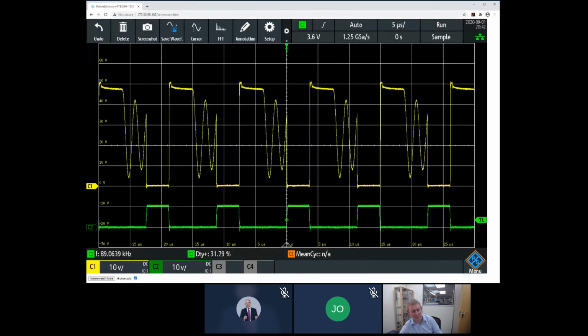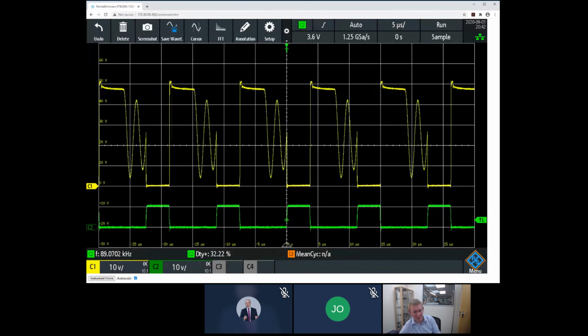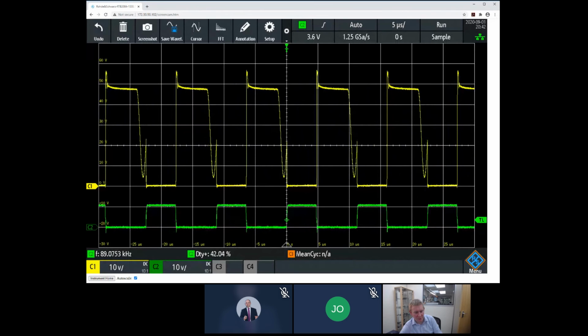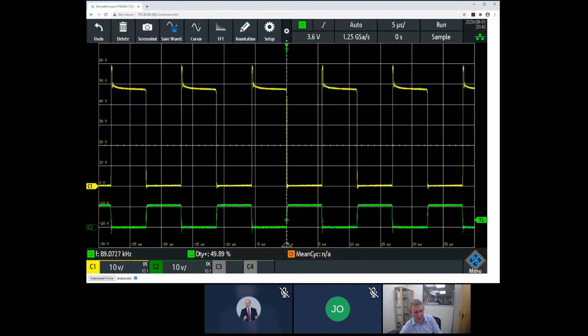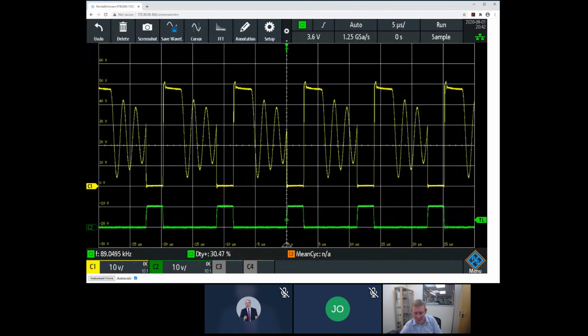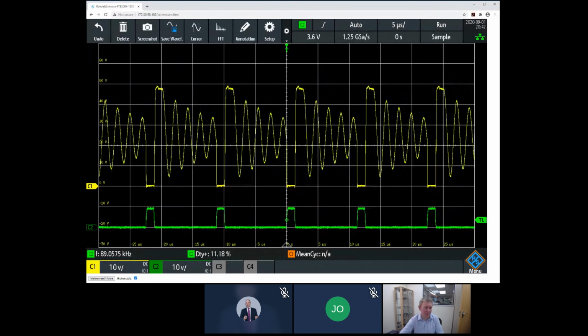The controller is measuring the output and adjusting the duty cycle of our switch to maintain the output at 15 volts. If I keep going, you can see we're just onto the edge now of, in fact, just there is the boundary between continuous conduction mode and discontinuous conduction mode. And if I continue winding up the load, the duty cycle doesn't change because of the way the input to output ratio works in this converter. If I go back down again, turn the load right down or off, you can see we go back to our normal state. I thought I'd include that at the end of this presentation to give you a feel of what a real switching converter waveform looks like.